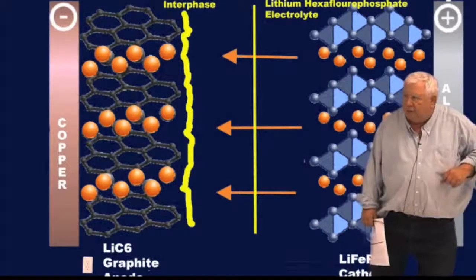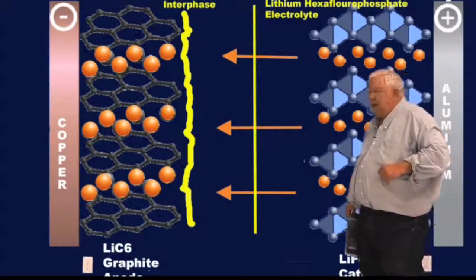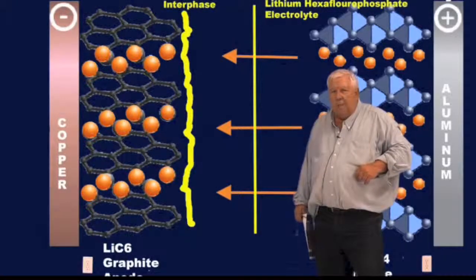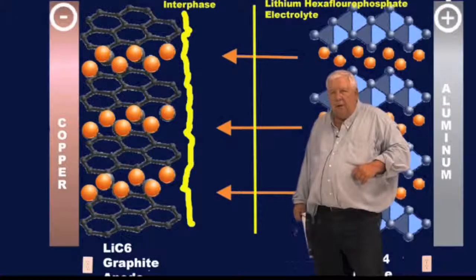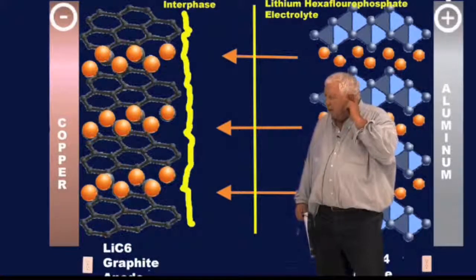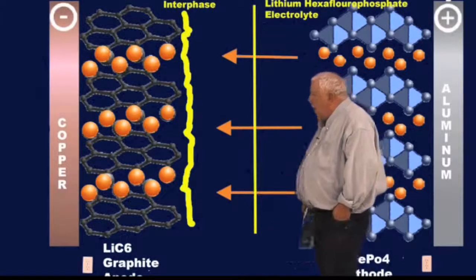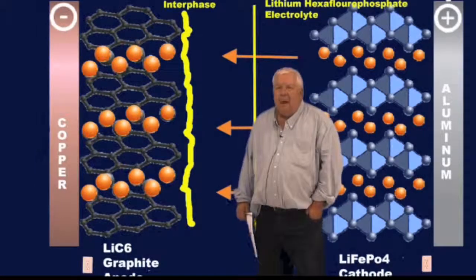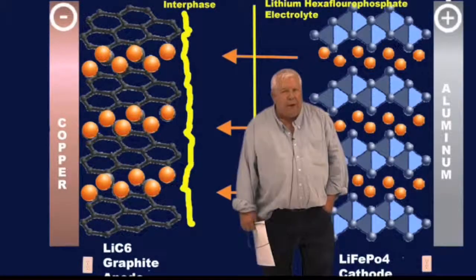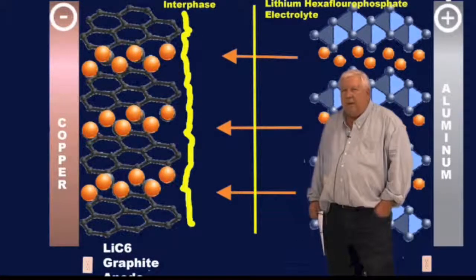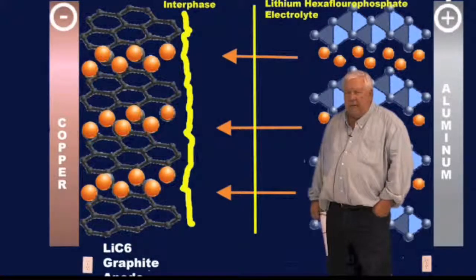And give you a little bit of an overview of what happens with overcharge and over discharge, and why those are the two no-nos with lithium batteries. The effects of temperature. Increased temperatures cause a lot of these things to happen more quickly, but the biggest problem is that our electrolytes again begin to gas, and most especially the ethylene carbonate at about 90 degrees centigrade. There's some other things that happen before that, and so we say the band of 70 to 90 degrees centigrade is a bad place to be with these batteries internally, certainly externally.